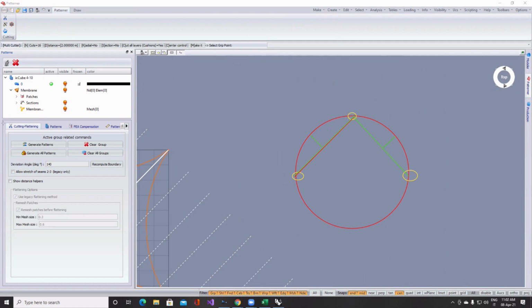So clearly, if the green is your panel and you make only a few panels, since we are making a linearization of the problem when we flatten it on the ground, we cannot make only 2 or 3 panels if we have a high curvature. We need to make more panels.